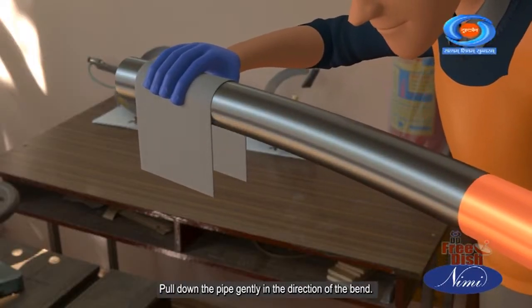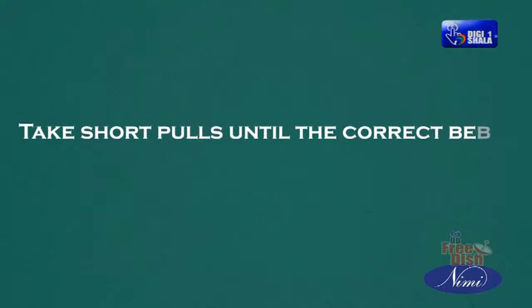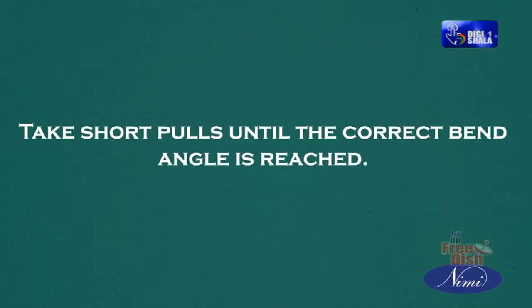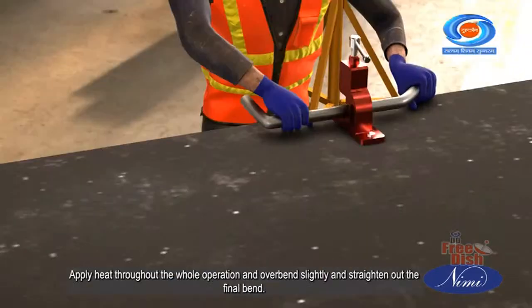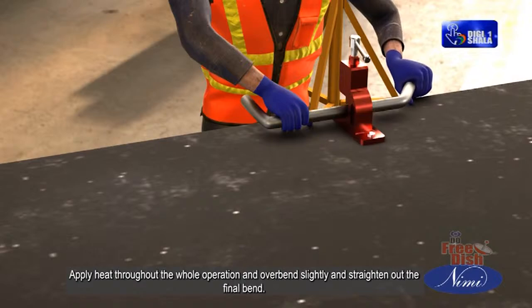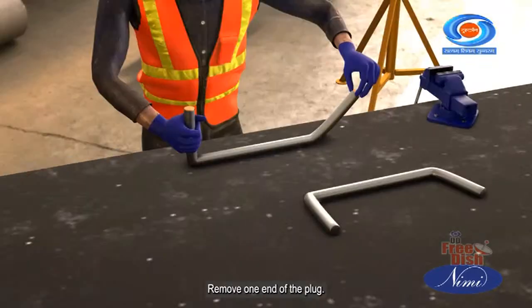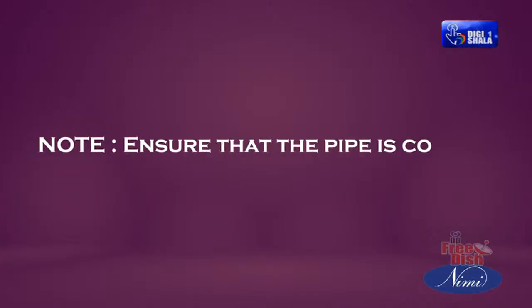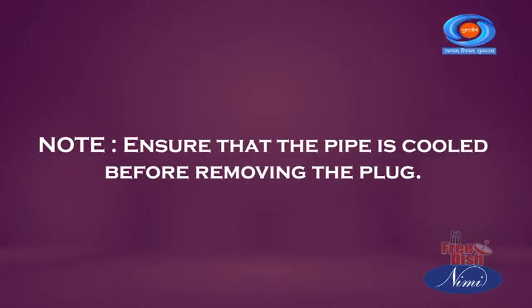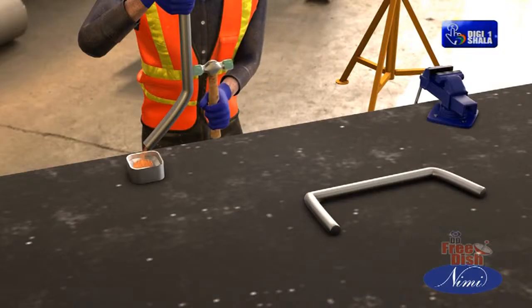Pull down the pipe gently in the direction of the bend. Take short pulls until the correct bend angle is reached. Check the bend radius with a template. Apply heat throughout the whole operation and overbend slightly and straighten out the final bend. Remove one end of the plug. Note: ensure that the pipe is cooled before removing the plug. Remove the sand by tapping the pipe gently with a hammer.